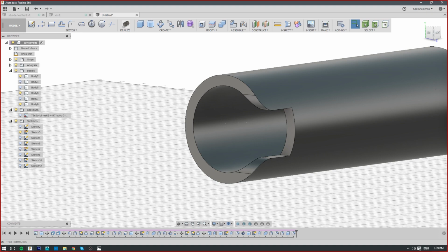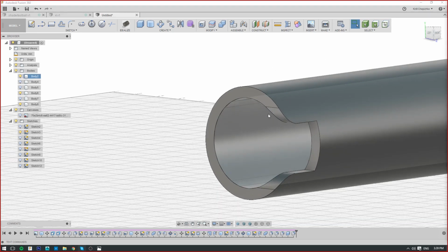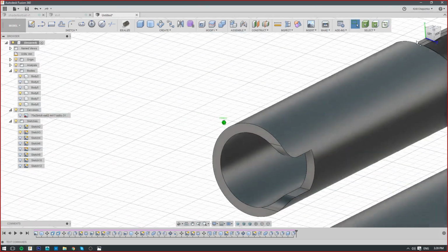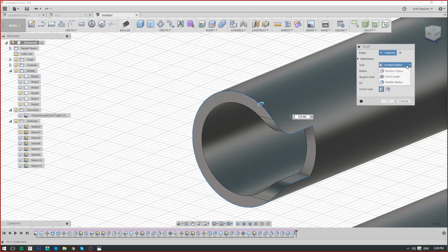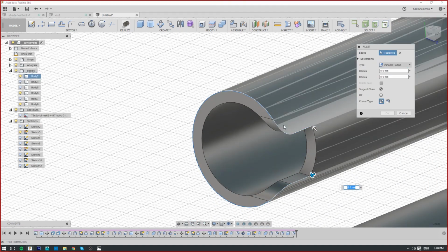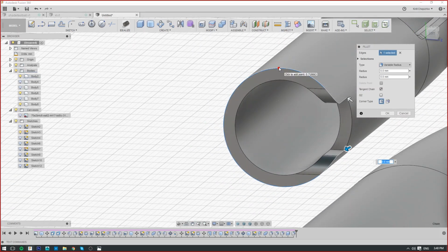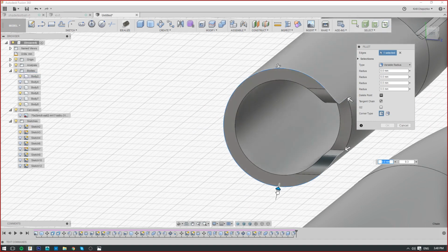Okay. So the last question you had was gradient chamfer. It exists more with fillets, I think, rather than chamfers. It's called a fillet with variable radius. It will ask me to place points where the radius starts to change.